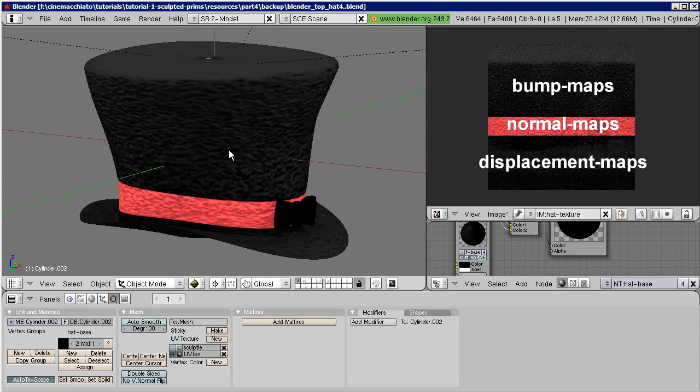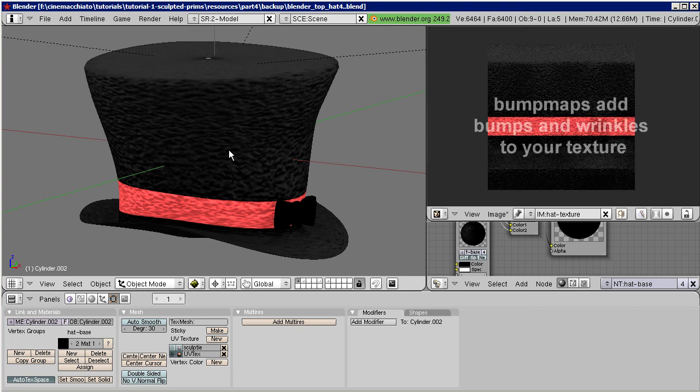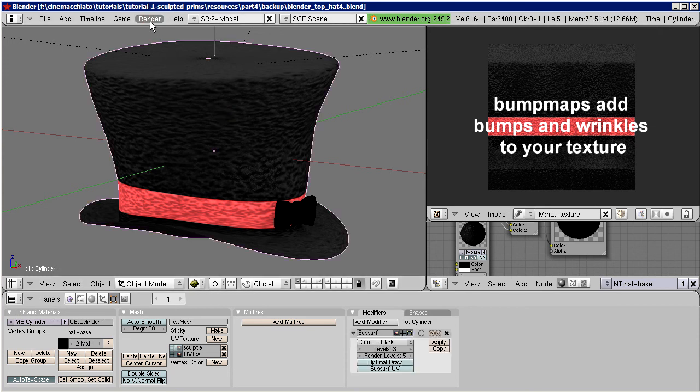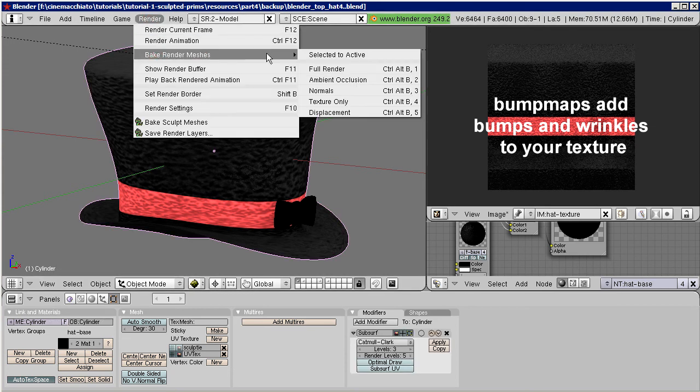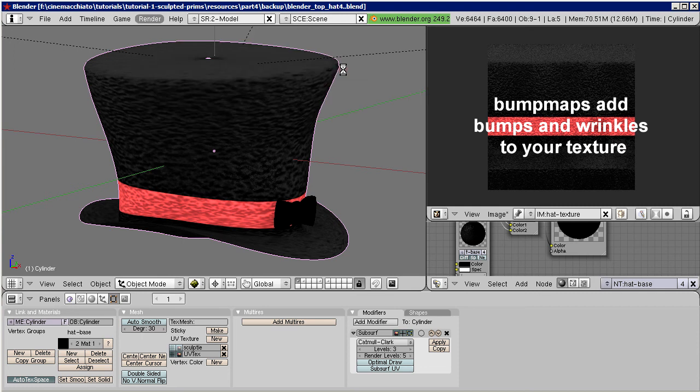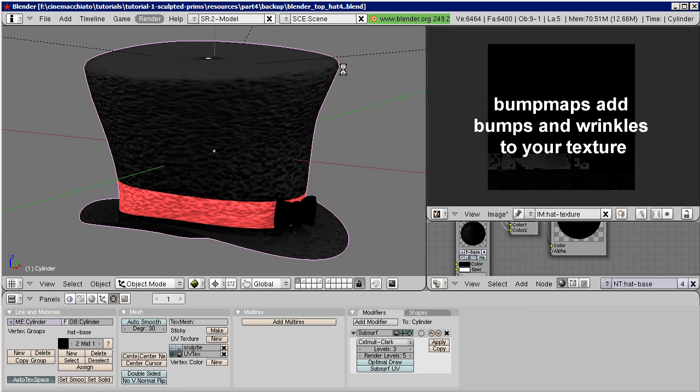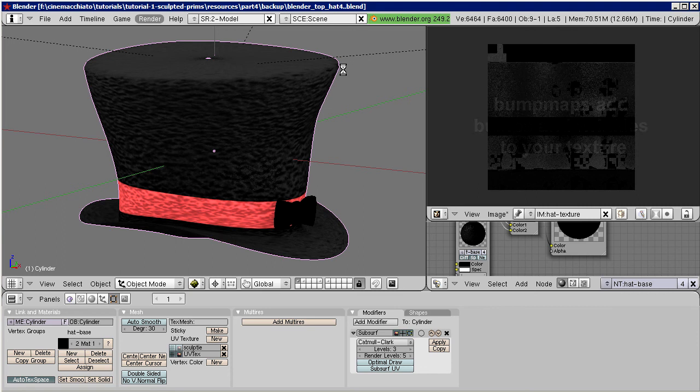Bump maps can be used to simulate what we just have shown with our high poly model. Blender will create a virtual mesh point for each pixel of the bump map, and raises or lowers this virtual mesh point along its vertex normal, depending on the pixel's color. As a result, a bump map simulates a surface with much richer detail than the actual mesh supports. So bump maps can enhance low poly meshes, and let them appear much more structured than they actually are.